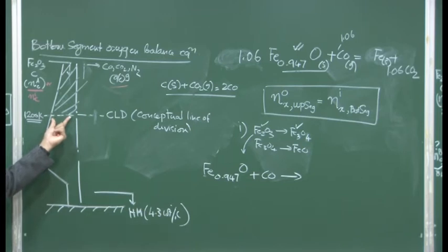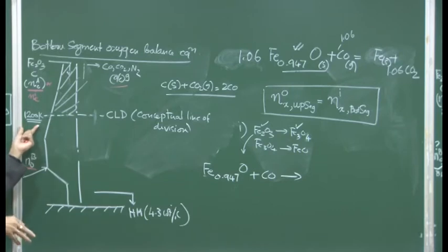It comes out to be 900 plus 273, 1173, but because these lines are nevertheless not so sacrosanct in a blast furnace operation, we are making an idealization. As I said, models are built on certain idealizations, and this is one of the idealizations, that we have rounded off the value of 1173 to about 1200.